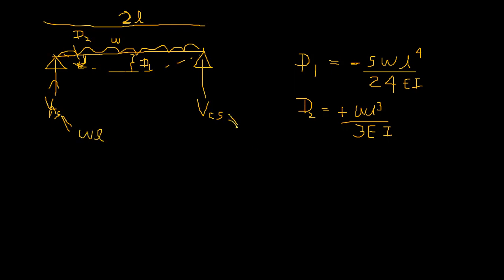This is also just WL, right? It's symmetric, right? So our first step is done. The primary structure is done and dusted. And we go back to the second. Here you don't have any loading. What you are doing is basically applying that unit force.